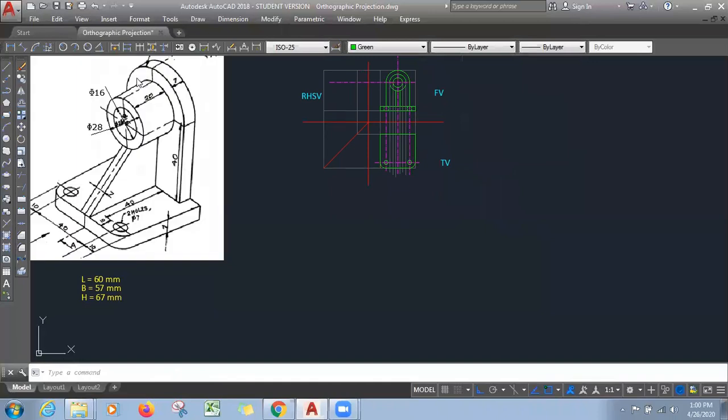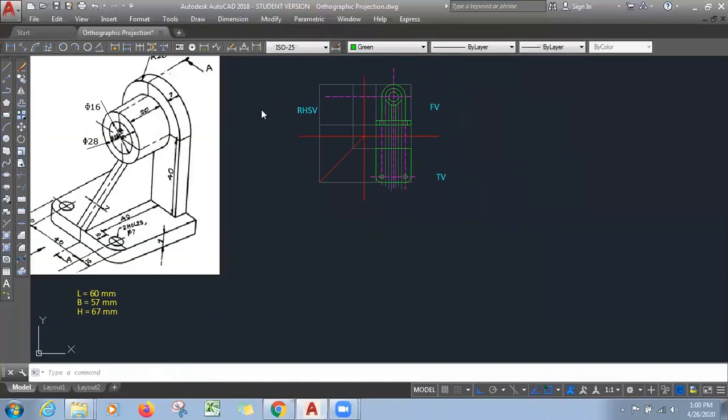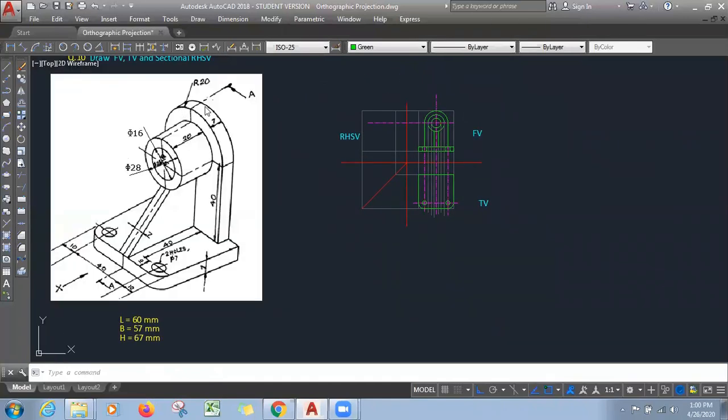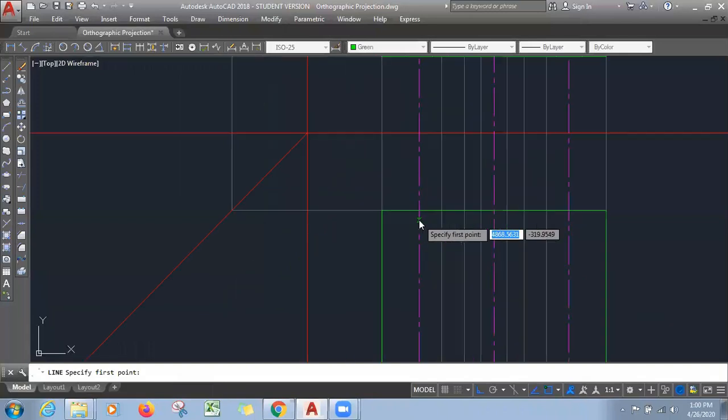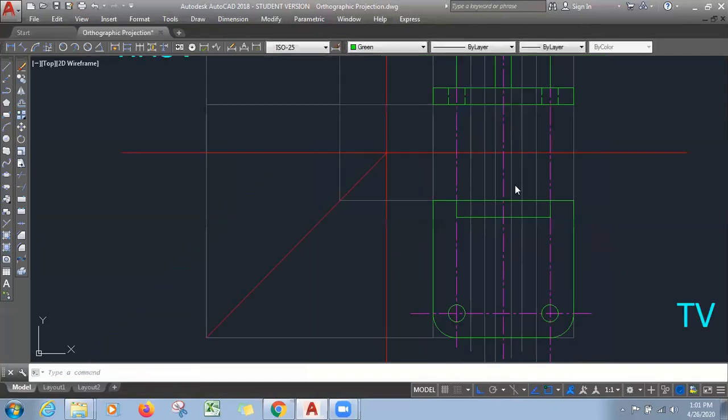You see. Now this cylindrical portion, very first thing is this outer one. This can be seen as a rectangle. This one. Take a rectangle having width of 7 mm and length of 40 mm. Take it because radius is 20. So length 40 we already have. You see, width is how much? 7 mm. Enter. So it is like this. Okay.